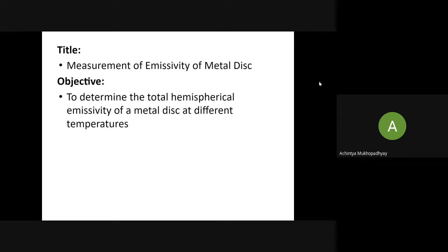That epsilon stands for the hemispherical total emissivity. If it is a directional one, then it is generally indicated by a superscript prime. That means it is written as epsilon prime. And if it is a spectral quantity, then it generally has a subscript of lambda. So a directional spectral quantity will be denoted by